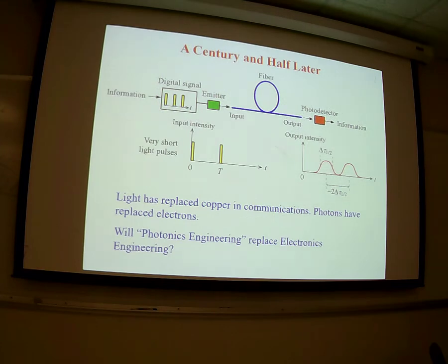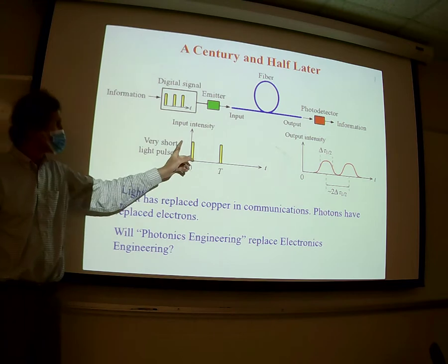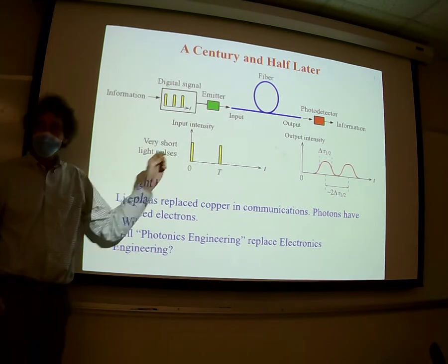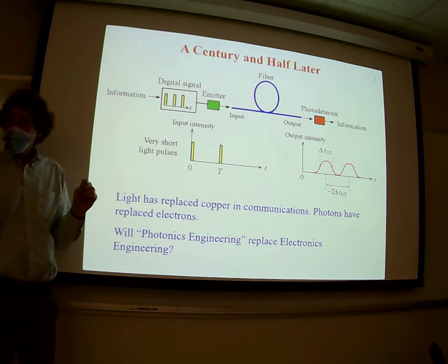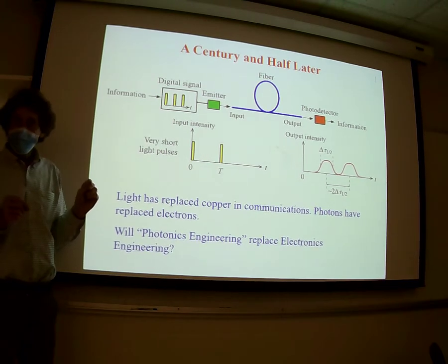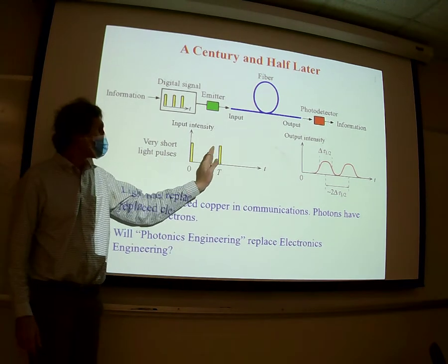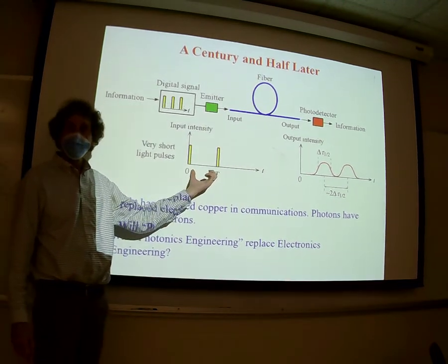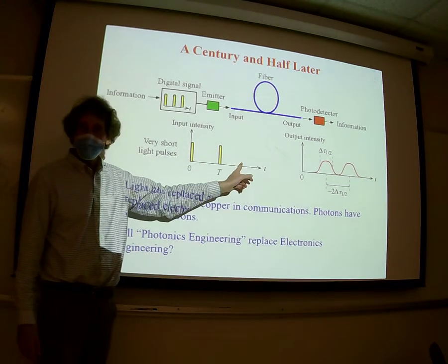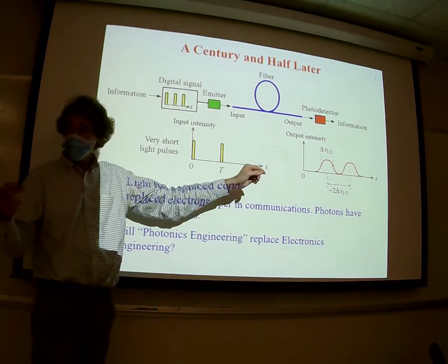All right. So how does information actually work in fiber optic guides, or just the fiber optic cable? You all see that digital information off to the left there? You guys are familiar. This would be considered baseband, something with ones and zeros. Here is the pulse, here is the pulse. It's sent. Now, there are a lot of different ways to code information. I can say if I get two pulses separated by t, that's a 1. If I get only one pulse separated by distance t, it's a 0. Something like that. That's one method. You all follow me?